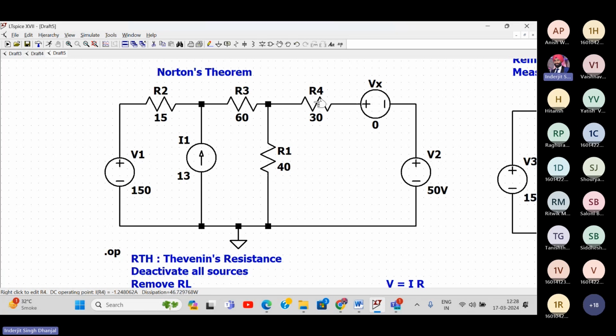So this is the amount of power we get directly, the maximum power. That is the only thing we want to find, the P max, and that will be available over here directly. So that's the only change we do in the maximum power. Rest all the steps remain the same. Actually, maximum power is just all the steps for Thevenin's theorem only. At the end, we find P max, VTH square upon 4 RTH.